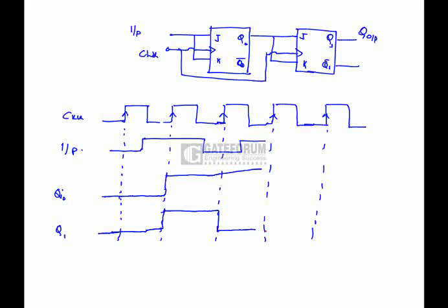Question is, a T-type master-slave JK flip-flop is shown in the figure along with the clock and the input waveform. The QN output of the flip-flop was 0 initially. Identify the correct waveform for the output. See, the flip-flops we used here change their next state, which means the response is going to change on the positive transition of the clock.